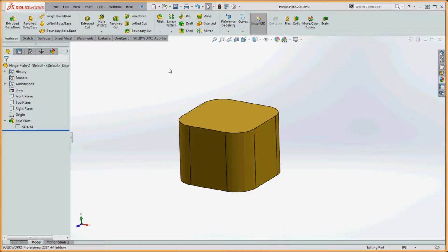So the way you do that, and it's going to be in a very similar way that we've done before, is we want to choose a surface on our model so far to put those holes in. Or if you wanted to, we could still pick like the top plane, front plane, or the right plane to do that too. Remember, those planes are in the middle of our model. But we're not reliant upon these planes. Now that we have some surfaces already created here in SolidWorks, we could choose much more than just the 3 planes. We have the top and bottom of our part, we have the left and right side, we have the front and back, and we also have these surfaces over here too where the fillets are, as well as our plane. So we're adding more complexity to our model now.